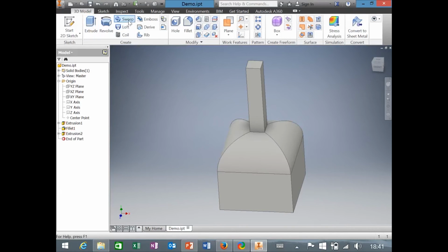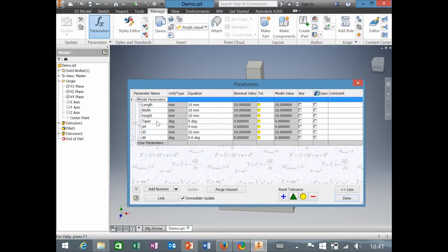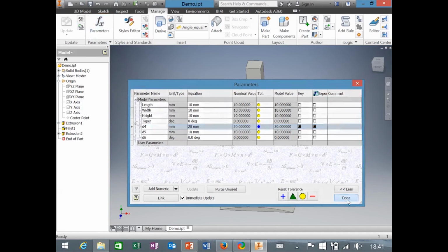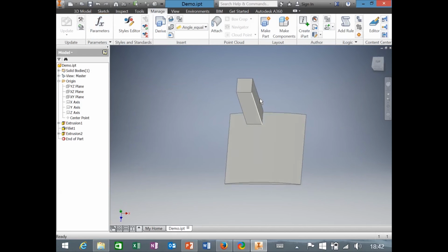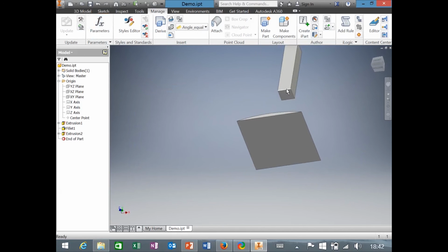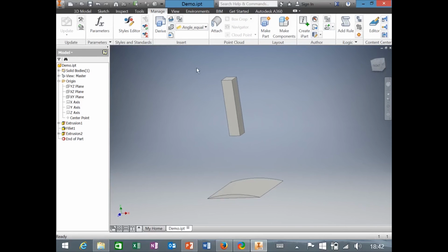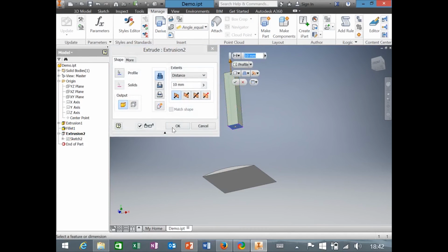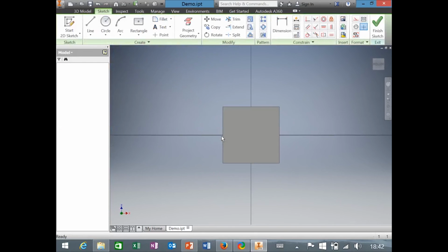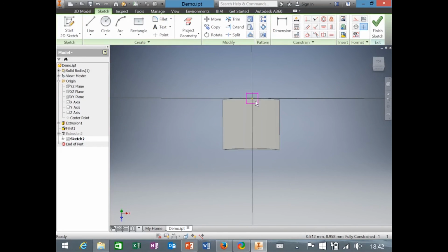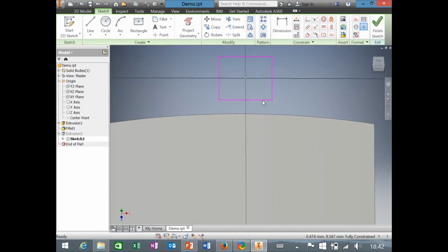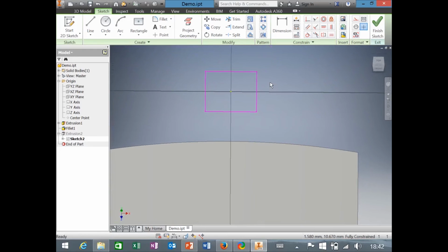like that, and go back and change the fillet so that there is no longer that square there. So make it, say, 20. Wow, that's interesting. Never seen that happen before. Well, clearly it's broken, but it didn't complain about it for some reason. Yeah. So in this case, that feature disappeared, and I'm actually kind of curious as to why it's still there. Oh, interesting. That geometry is actually still there. No, it's not. OK, yeah. So you can see here that the color of this has changed to pink. That means that geometry is no longer available. But for some reason, it didn't complain about it. It just broke it.